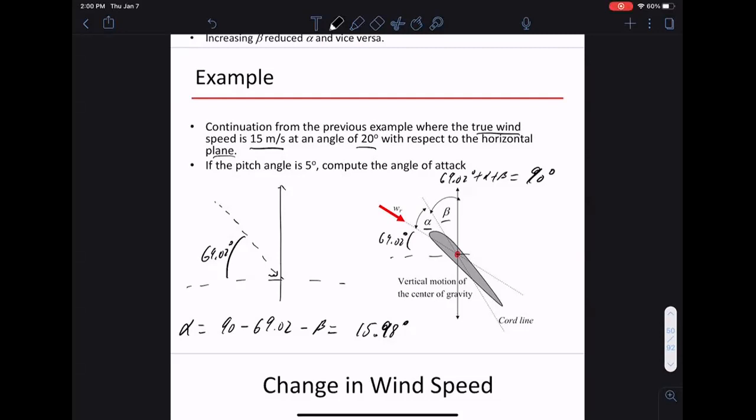Whereas with the angle of attack, it's harder because the angle of attack is referenced to the relative wind. So the angle of attack may jump around depending on the wind direction, whereas beta is easier to think of as a control variable. You're controlling beta to track power output. So that's why it's easier to think about when using the wind turbine in practice. Both are equivalent, but in turbine control, we almost always talk about the pitch angle instead of the angle of attack.